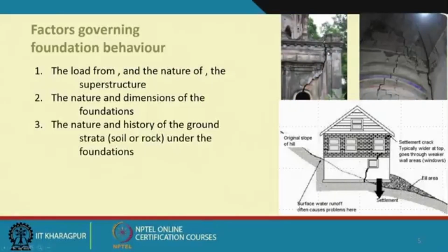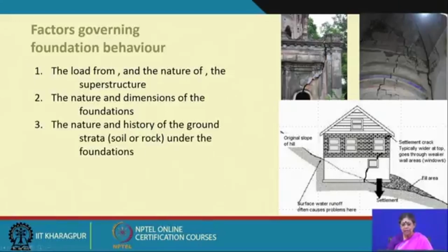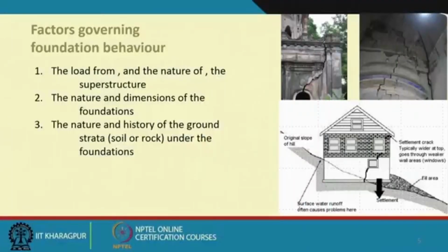Here again you see this type of crack that we have seen, and this is a structural failure. One has to carry out some sort of investigation to see what the actual reason is. But these are the initial signs, and again, as I mentioned earlier, one has to ascertain whether it is a live crack or a dead crack with continuous monitoring.